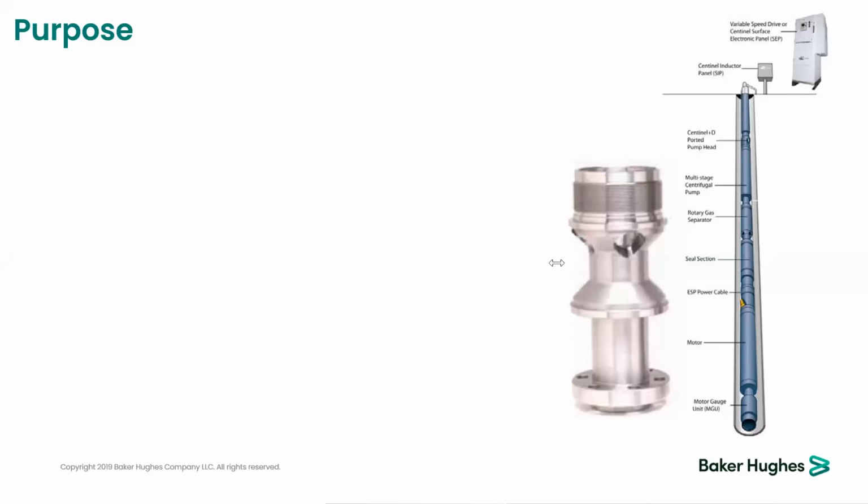Missing or damaged, absolutely you shouldn't have. You can have a slight wear, a slight effect, but missing or damaged washers shouldn't be present at all during a pull out.